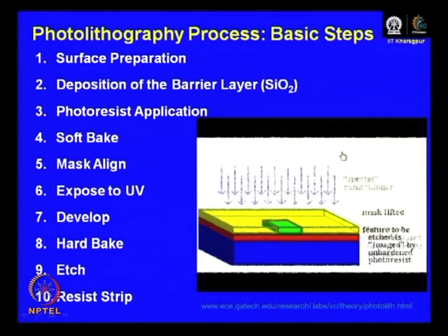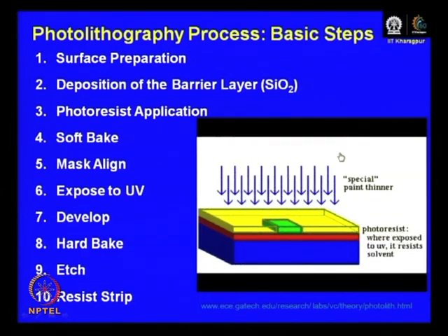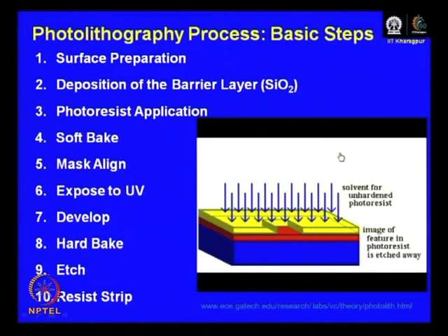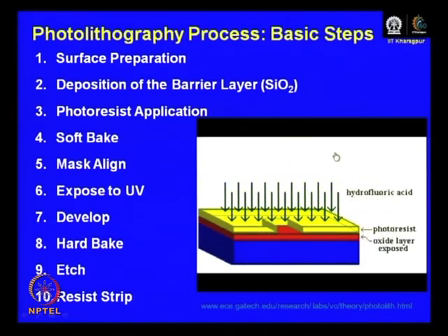Then the mask is removed, and then you apply different thinners or different chemicals to etch first the photoresist layer, then you also etch the oxide layer, so that for your diffusion reaction, which is going to create the other type of doping in the wafer, over these areas, if you have started with a p type wafer, you would like to dope it with something n type, so that you have p-n junctions. So, first you etch the photoresist layer, then you also etch the oxide layer, maybe with hydrofluoric